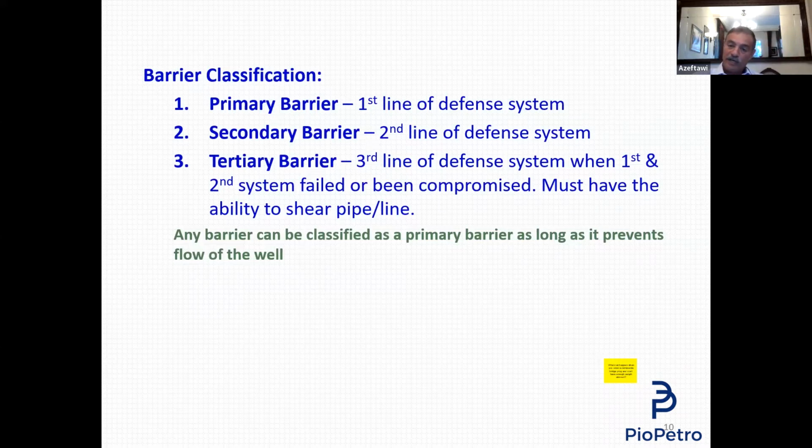The way we do it this way, what if a situation happens where you need to prevent a blowout, but you cannot access your control cabin, or the area you are working in is full of exposed hazards. You cannot access it for some reason. That's why you can seal your rig, your well, from a remote, safe area.